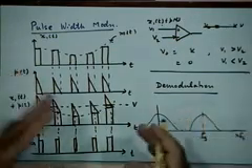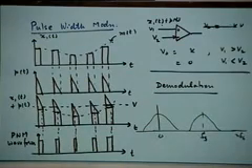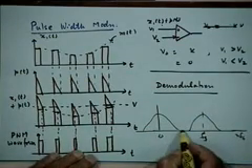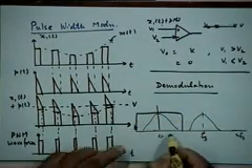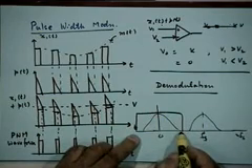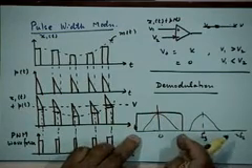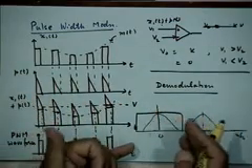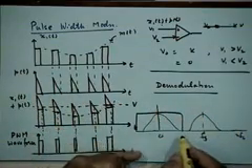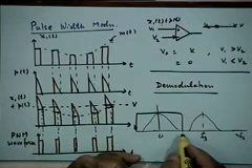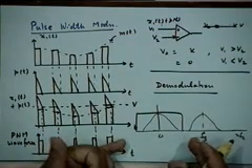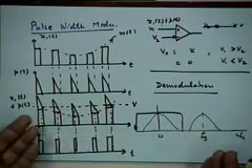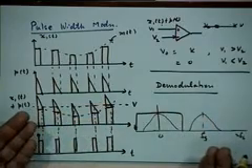It is a periodic spectrum, and the demodulation was based on the fact that the spectrum of interest for the continuous signal lies in the central lobe around the baseband. So, all you have to do is remove the components above the bandwidth of the signal by passing it through an ideal low pass filter, and you have your continuous time signal back.